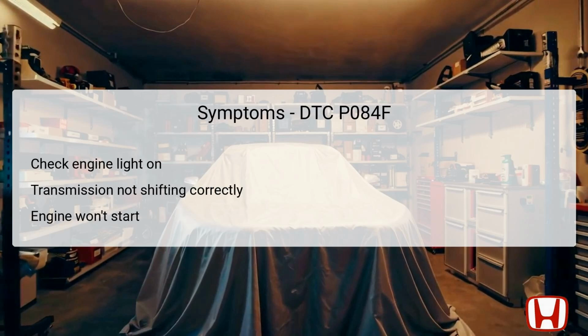When DTC P084F is present, drivers may experience a number of noticeable symptoms. A common symptom is the illumination of the check engine light, which serves as an immediate alert that a fault has been detected in the vehicle's systems. Furthermore, improper shifting of the transmission may occur, leading to difficulty changing gears or a total inability to shift, which is particularly dangerous while driving.